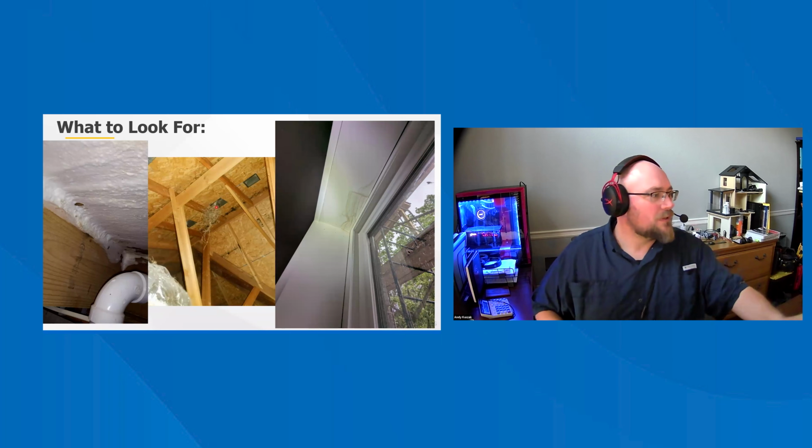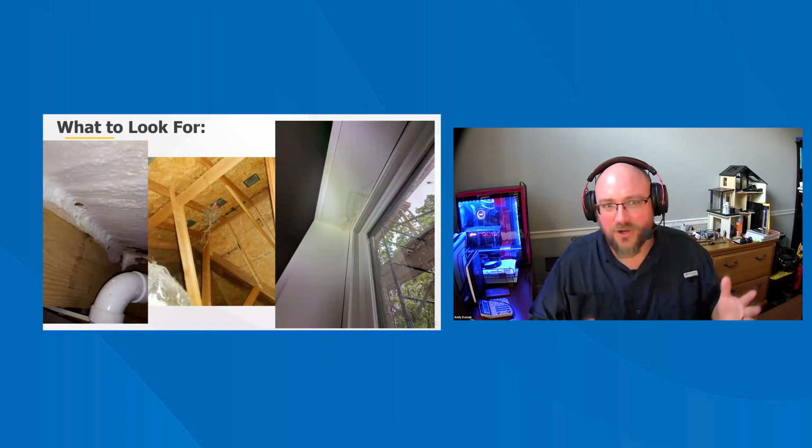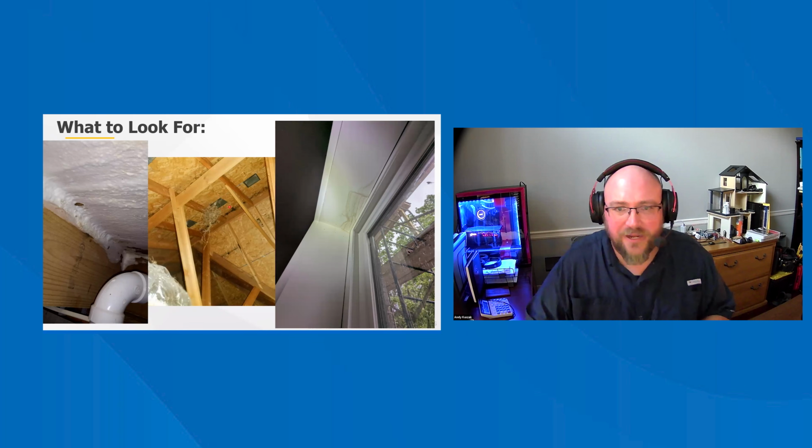That will cause all kinds of problems. So, any penetration, you always want to make sure there's a bird screen. Something like that will stop any type of nesting from happening in those areas. And if it's damaged, it obviously needs to be repaired.